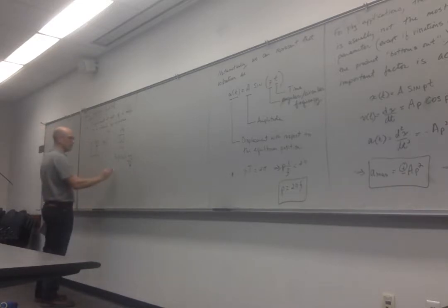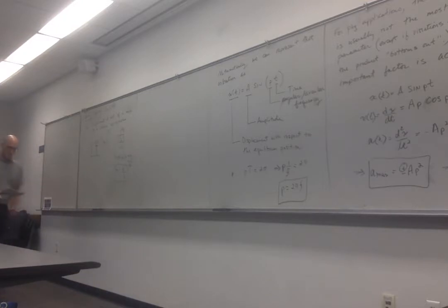So from there we find that the static deflection is equal to the weight divided by the spring constant. And again, that's something that's easy to do in the lab. We're going to just use that factor quite a lot in our calculations.